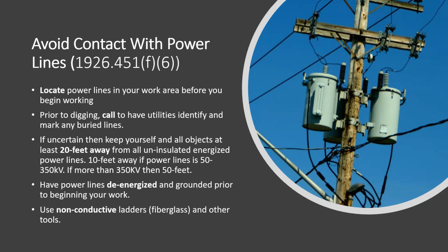If uncertain, then keep yourself and all objects at least 20 feet away from any energized line. When we don't know how much power the energized line carries, and it is energized but uninsulated, keep away; if it is insulated, then 2 feet is enough, right?